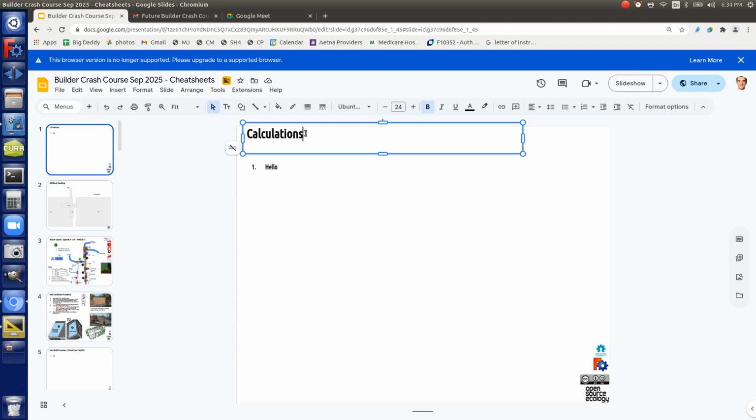Yeah. So what if that post was made of steel? Here we're just looking at the biggest picture considerations. How much could it support? As an I-beam, or just in its same shape? Well, they do the I-beam precisely for that reason, where they cover more footprint space so it doesn't bend one way or the other. Compared to a straight rod, they spread that metal out into an I, which has more area that resists buckling, right?